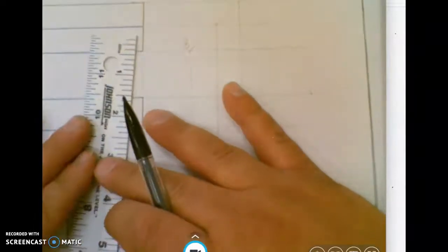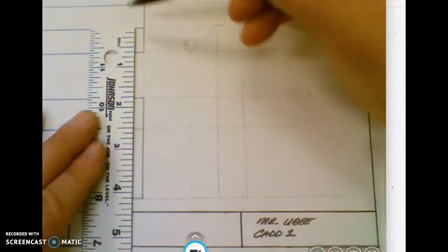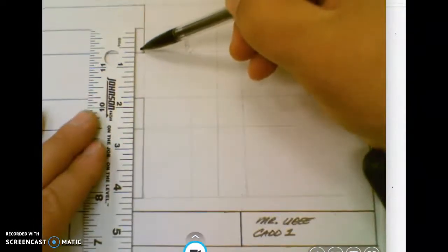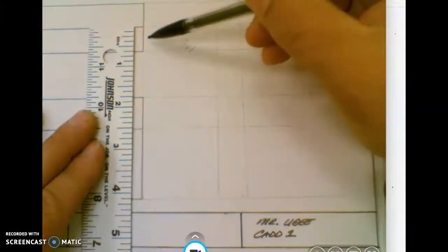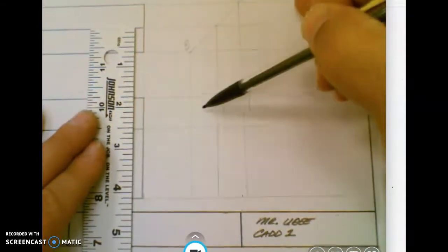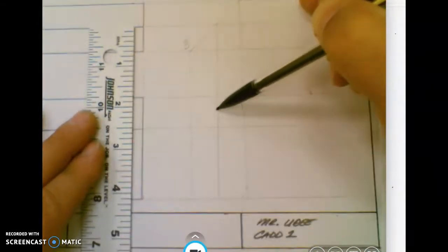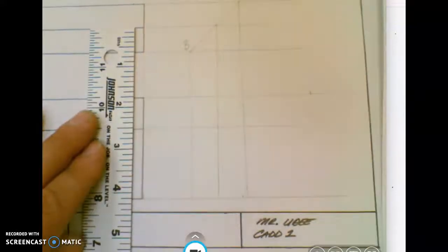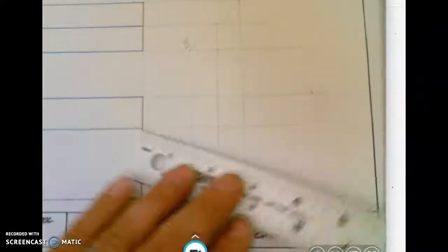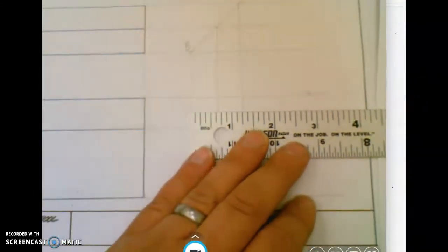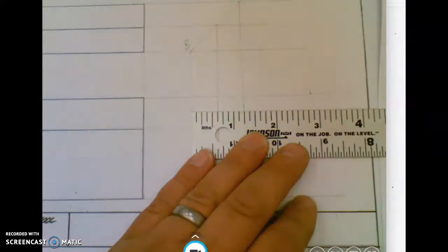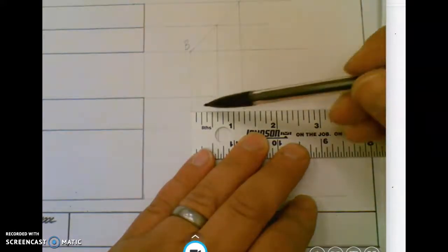I can verify that measurement in my top view. We can see it's 5/8. That 5/8 is in this section here, comes down, so I'm going to verify my 5/8 right here between those two construction lines. Measure that out, and you can now see on my screen, I'm at 5/8.